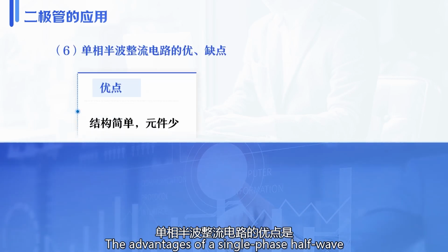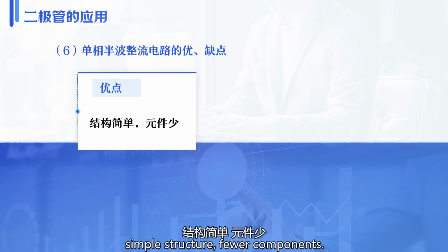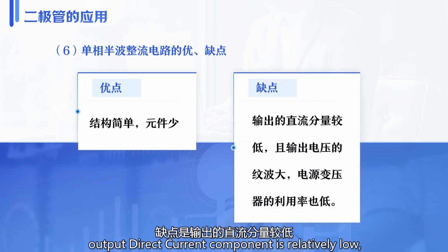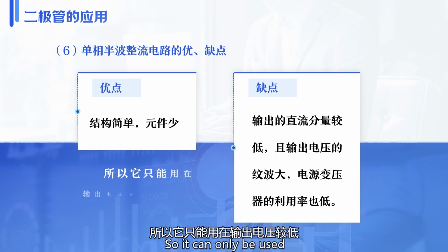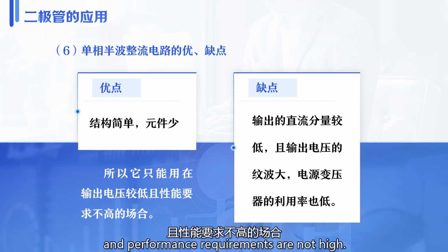The advantages of a single-phase half-wave rectifier circuit are simple structure and fewer components. The disadvantage is that the output direct current component is relatively low, and the ripple of the output voltage is large. The utilization rate of the power transformer is also low, so it can only be used in applications where the output voltage is relatively low and the performance requirements are not high.